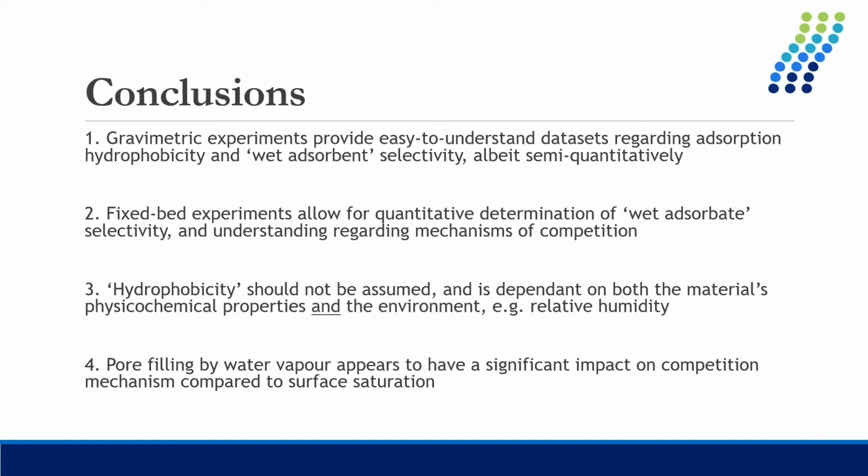Hydrophobicity, which is often a sort of assumed material property, should not be assumed. It's not immutable, and it's dependent both on the material that you're working with and its physicochemical properties, and the environment. So as you increase relative humidity, you can't assume that your material will stay hydrophobic. And finally, pore filling by water vapor appears to have a significant impact on the adsorption mechanism and also on the competition mechanism compared to simply surface saturation.